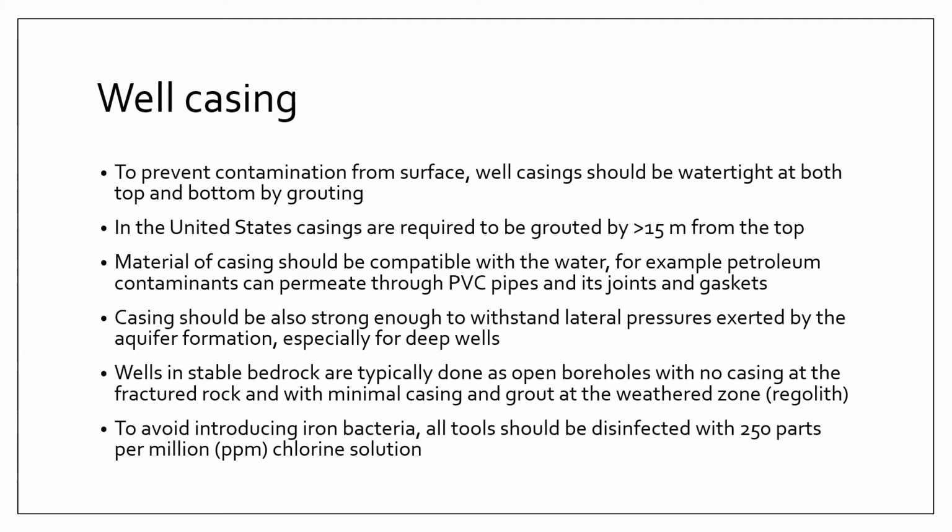Otherwise, if the whole well is in contact with the aquifer and other unimportant layers, we are risking contamination from surface waters as well as contamination from other layers.